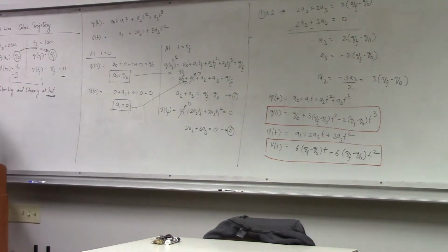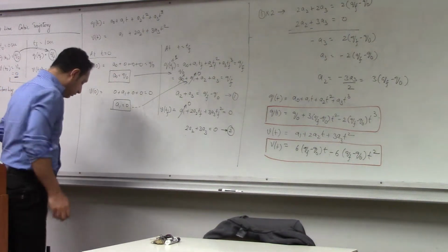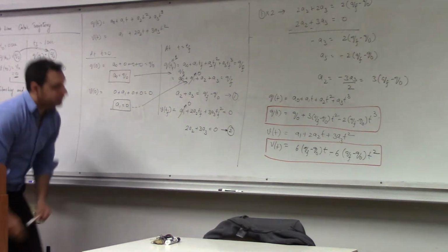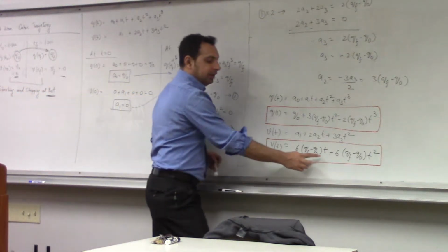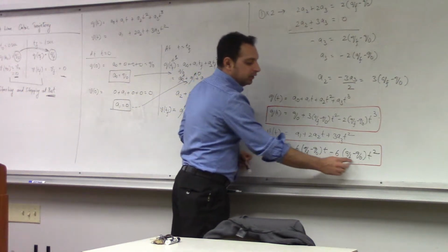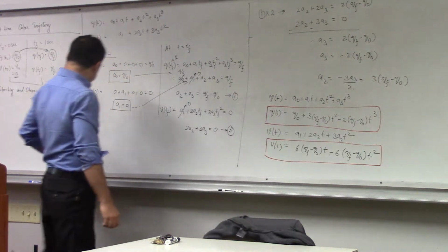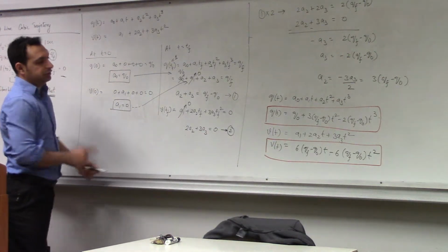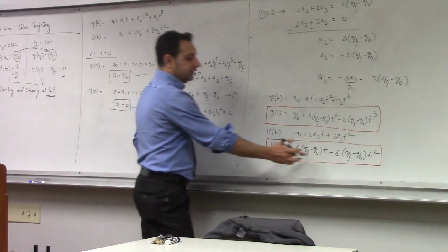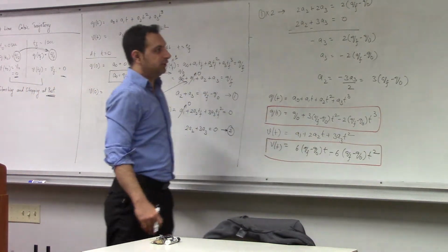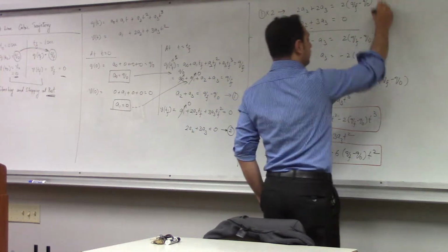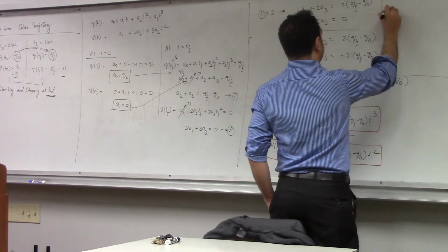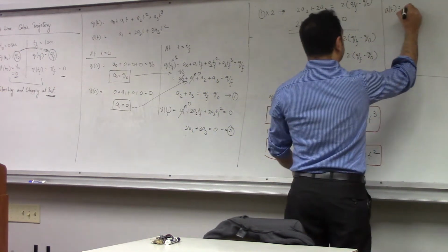Okay. So when you try to plan the motion, you can just set up this equation and automatically the coefficients are calculated by this. Because you have a1, a2 already defined in terms of your final position. Same thing you can do, differentiate this one more time and you'll get your acceleration. If you want to plot the acceleration, a of t will be equal to